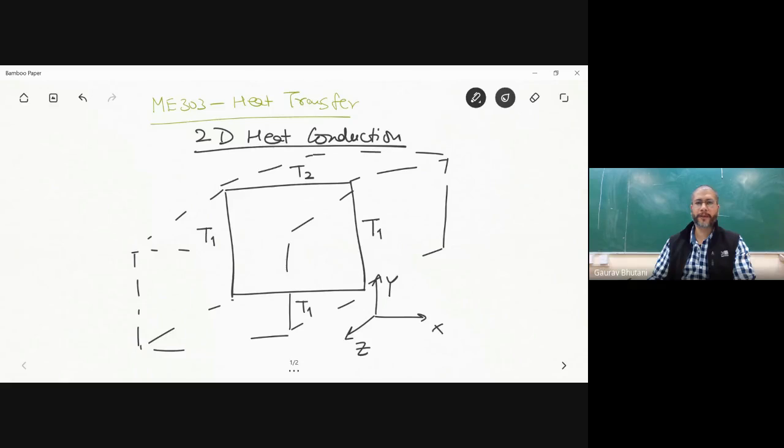Could be another fluid that is melting, which melts at a higher temperature than water. So let's say this is 20 degrees centigrade, or any temperature above T1. Okay, and since this rod that we're considering is very long, the temperature gradients along the Z direction will not be there, because it's an extremely long rod, so you can neglect the temperature gradients along the Z direction. So it essentially becomes a two-dimensional problem, so we don't have to worry about the Z direction.